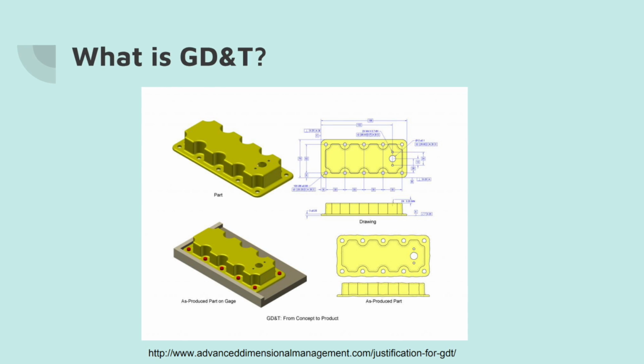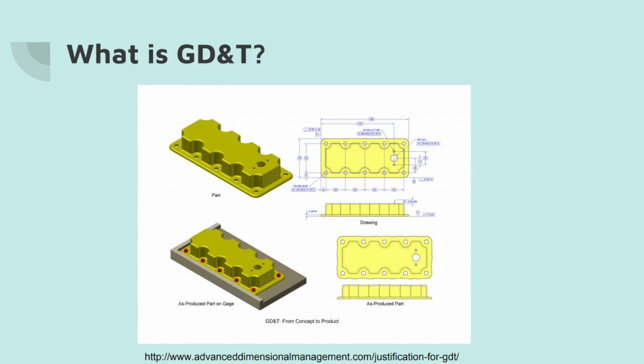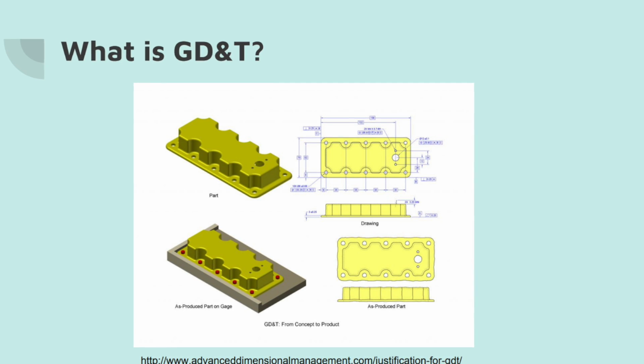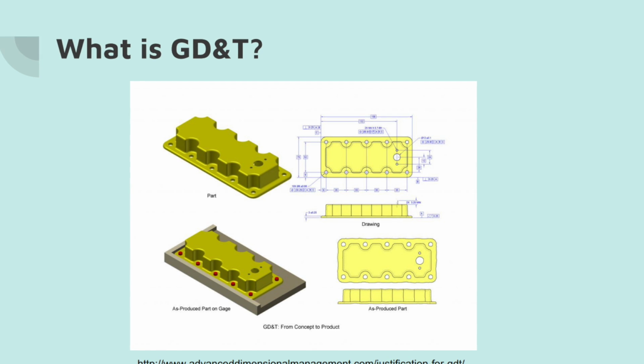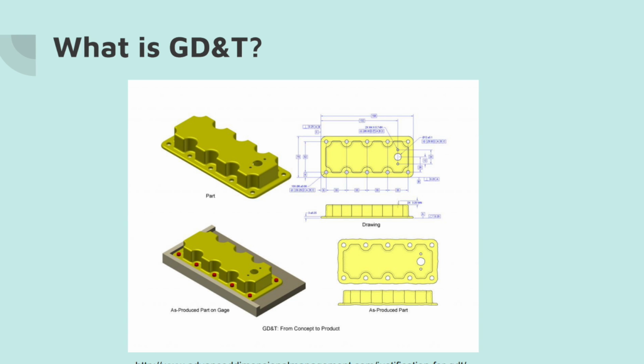However, there is an abundance of variation due to manufacturing processes inhibiting the part size from being the exact intended value. Because of this variation, tolerances must be used. Tolerances define the limits in which the geometric dimension is able to vary while still producing a good part. Tolerances are the difference between the maximum and minimum limits.